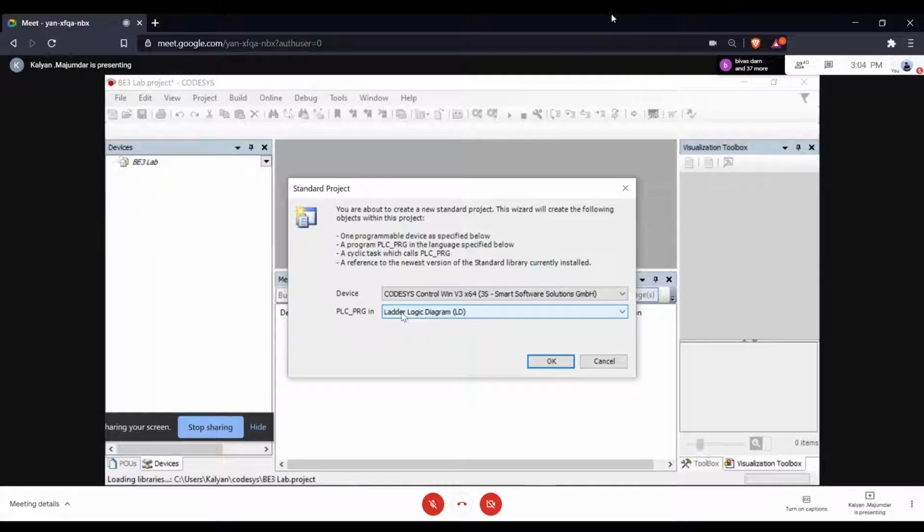You're developing logic, but where will this particular logic be executed? What's your target device? Normally, this is some PLC which you have, and you're developing the program for that particular PLC. But in our case, since we do not have a physical PLC, we'll be using a soft PLC that runs on our computer under the Windows operating system.